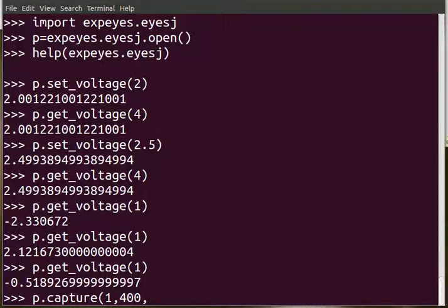And now the next question is, when you read these 400 points, 400 times you are going to measure the voltage, what should be the time interval between subsequent digitizations? Let us take that as 50 microseconds, because it is only a 150 Hz signal. The minimum value you can give here is 4, and we will give say 50 because it's a low frequency signal.